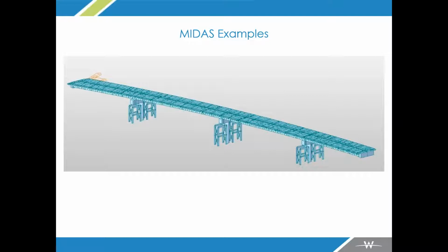The other thing here that's important is we're also capturing the relative stiffnesses of things. So that pier cap is much stiffer than this substructure. And what we found was we ended up having to increase the size of some of these members, not for strength, but for stiffness, because we want this steel tower to suck up the load. And what we're seeing happening is as you put a truck out here on the edge, because this pier cap was much more rigid, it was pulling more of the moment into the pier cap than it was putting into this, because it's all deflection based there.